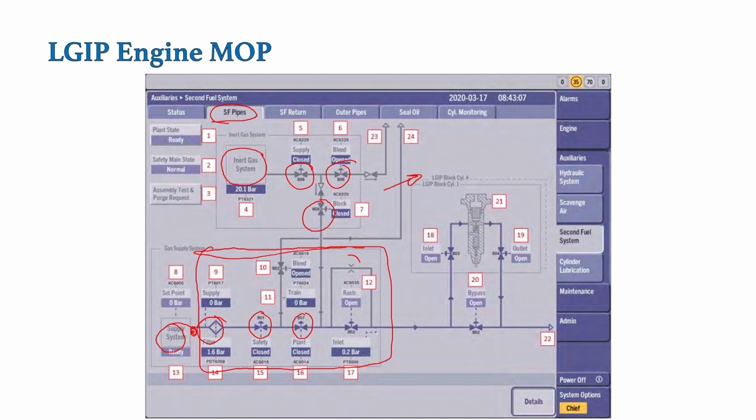Then we have this orifice which is there on the fuel valve train for gradually filling of the main engine, so that pressure fluctuation is not there in the system. This system is basically too sensitive to pressure fluctuations. Any kind of pressure fluctuation is there, we won't be able to start the system. So for that purpose, this orifice is there, which is very helpful during filling of the main engine during starting process. With the help of this, the engine is filled very gradually so that pressure fluctuations are not there.